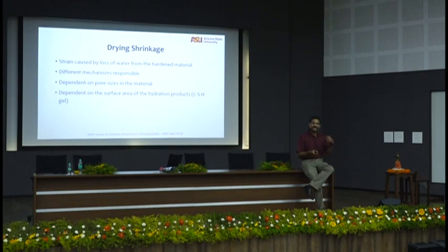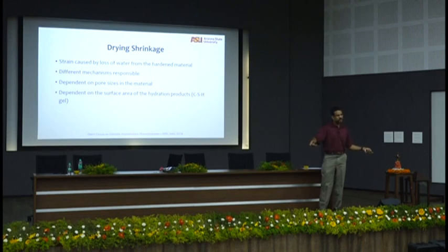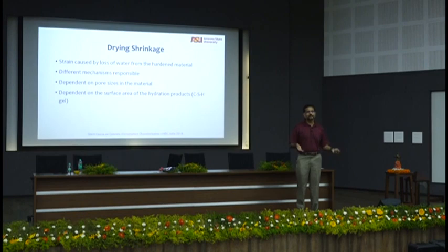Okay? You will get a measure of change in length. Perfect. And you can compare material A and material B and say this shrinks more and this shrinks less. But you don't know anything about the microstructure that might make it crack or not, right? So, the test, yeah, there is a standard, there is a test, you can report the results, you can publish the papers. Overall, waste of time.